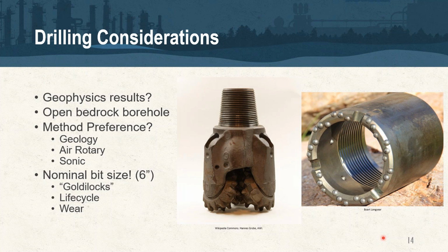So some preferences for installing these wells typically are personal to your geologist or engineer. In the part of the country that I typically operate in, we find a lot of air rotary installs. So I'm obviously deferential to that technology. Definitely makes a nice clean borehole you can easily blow out. But other places, people are using sonic, whether it's for coring or installation as well, and that works just fine. I know Bill has some experience with that, which he can talk to as well. But for me, getting a nice clean air rotary hole that's available to me for geophysical characterization is extremely important.